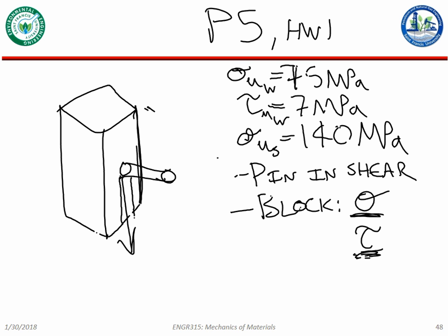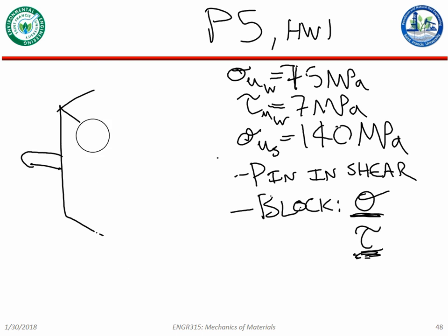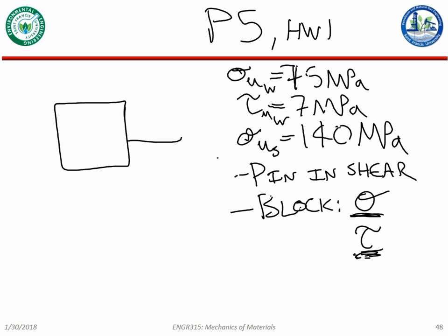So our approximation for that, like we said in the first thing, I think, is the cross-sectional area of the material that this pin would have to travel through in order to exit the block in the direction that it's being pulled. So if I was to look at this from the bottom, so this is a bottom view, pin, it would have to go through that area of material.